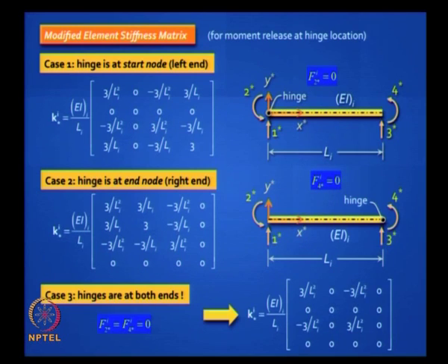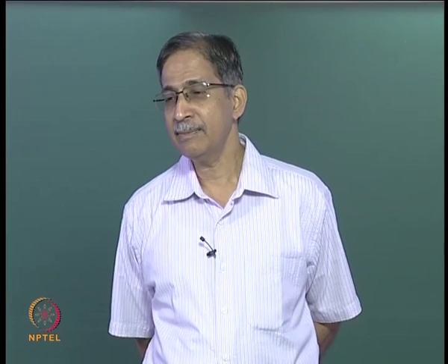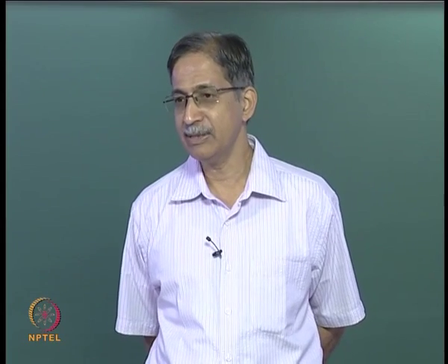So if you recall, we need to modify the element stiffness matrices. Essentially, one of those rows and columns will become full of zeros, corresponding to the release degree of freedom. So if you have a hinge at the start node, it is the second row and second column that gets released. Not only that, from 4EI/L it goes to 3EI/L, the flexural stiffness, and 6EI/L² becomes 3EI/L², etc.